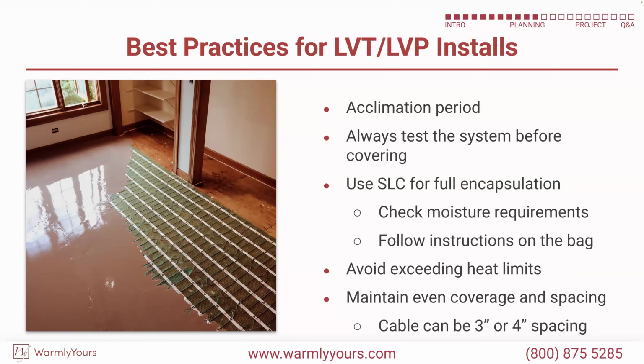And you're going to try to maintain that coverage super even. Cables can be spaced at 3 or 4 inches, so that's what you're going to want to make sure you're maintaining. Yeah, so do even spacing, because if you decide, hey, I'm not going to put any wire here, where there's no wire, there's no heat. The heat only travels about 1.5 inches laterally from the wire itself. That's why the cables are spaced 3 inches apart.